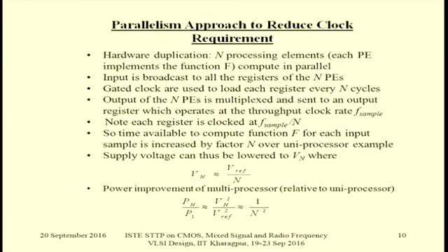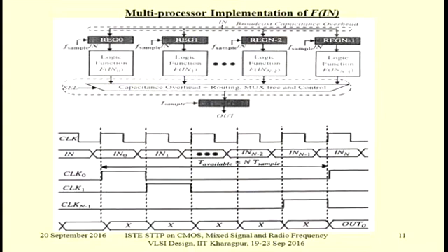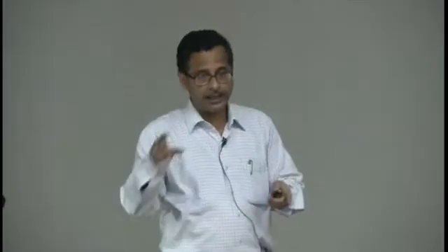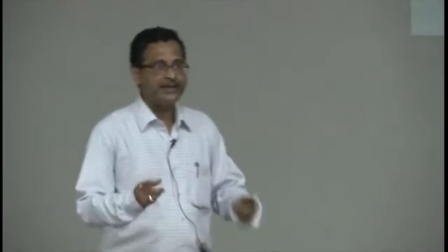So what we gain from here, see, earlier if say one logic function block was kept, it was having available a time of say 1 nanosecond. The available time is 1 nanosecond. Now if you allow a parallel architecture consisting of 10 similar identical blocks, then how much time is available now to each of the logic units? Not 1 nanosecond, but 10 nanoseconds. So an extended time period is granted to each of the logic functions.